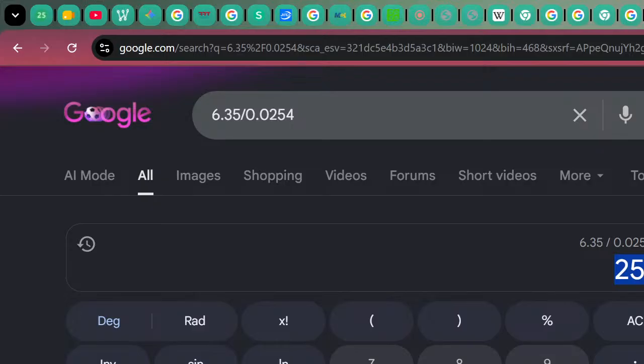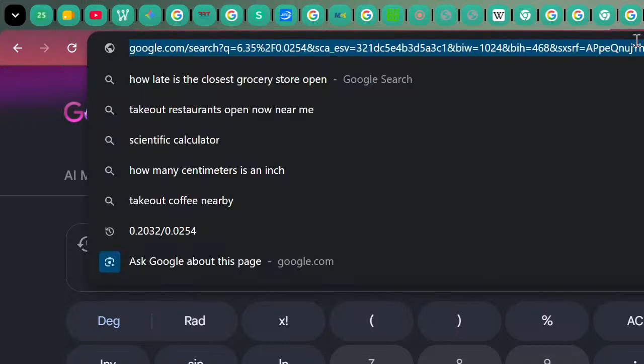But in industry, the values would be a little bit deviating from the actual specifications. So the thickness of gold is very small, very negligible, so that it can cope with different materials having different coefficients of thermal expansion, right? So it can cope with that because the thickness, whatever we are using, is very small. So it is very minute. It is very negligible. So now we will go into something called the tape test.